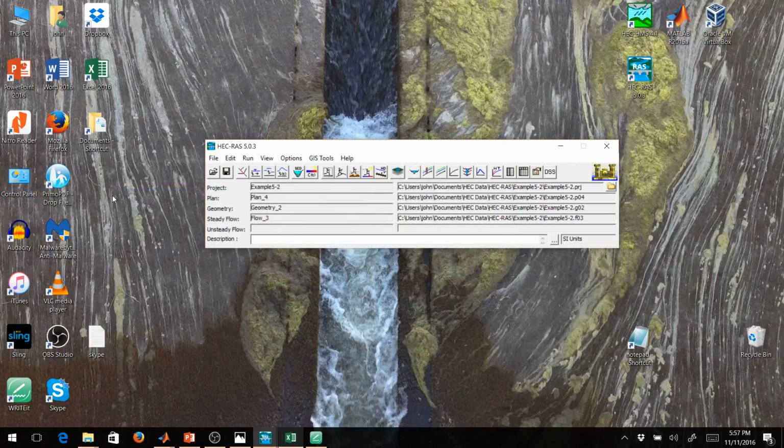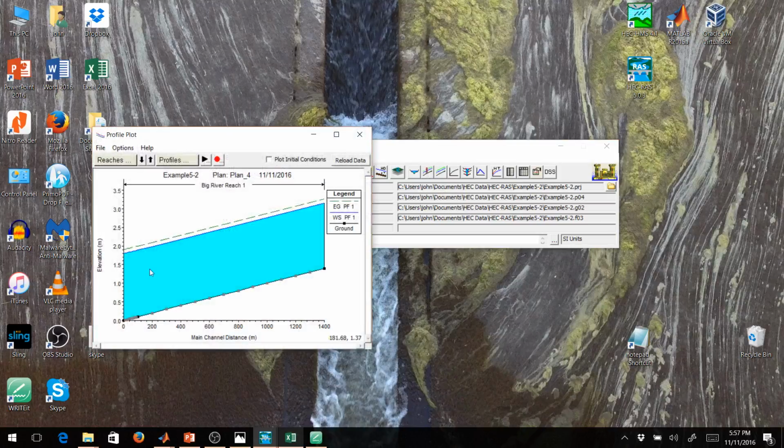I won't spend a whole lot of time going through this data because it's very similar to what we've already seen, but let's just look at the profile. We have our known water surface, and then it backs up here. It doesn't look exactly like the M1s that we've been drawing in class because it's a very mild water surface slope, and it'd be hard for me to draw this, so I usually exaggerate them on the board. But this is an M1 profile, and we could go in and find the flow depths at various locations along the channel as we did with the M2.